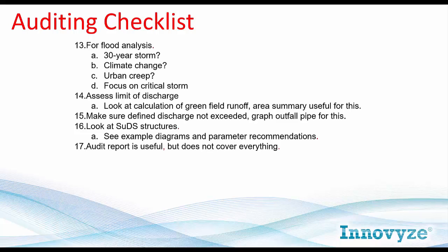So at that stage, you've run through the sort of automated process for designing the pipes. So you've passed stage 1 of the two tests. The second test, the no flood analysis. So again, you've got to pick a storm. Remember that it's not just one storm. There's going to be a variety of durations, summer and winter. So make sure they've all been run.